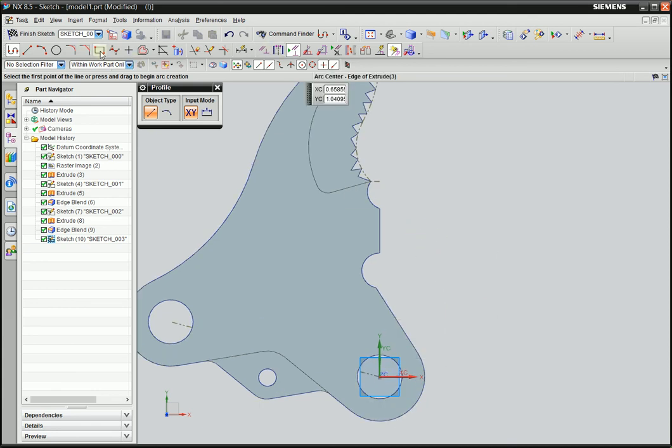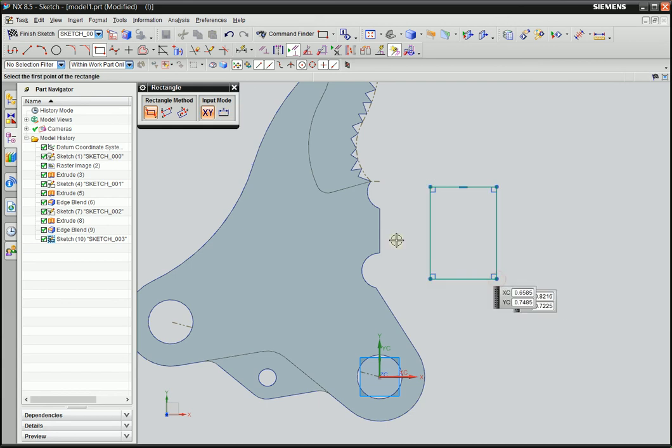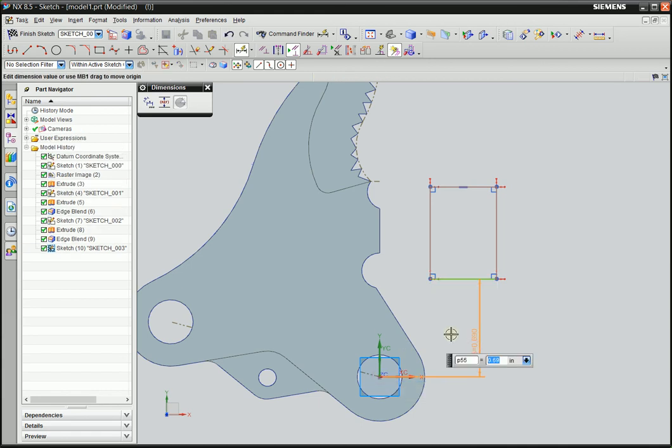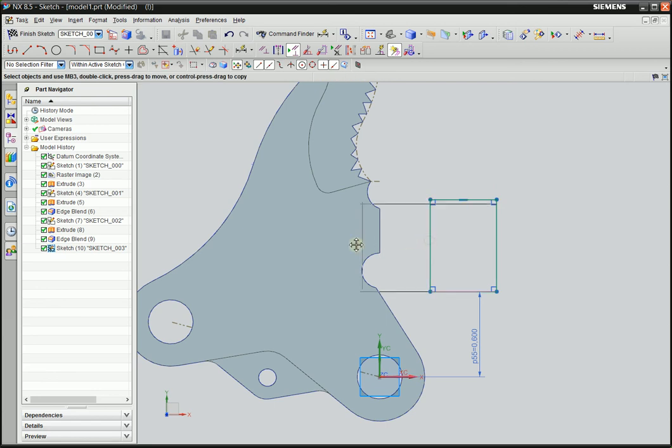Alright, so that's going to be a box. I just put a box first. Second, we put a dimension from here to here. That's going to be 0.6, and I want this to be the left of the y-axis, then put the dimension.